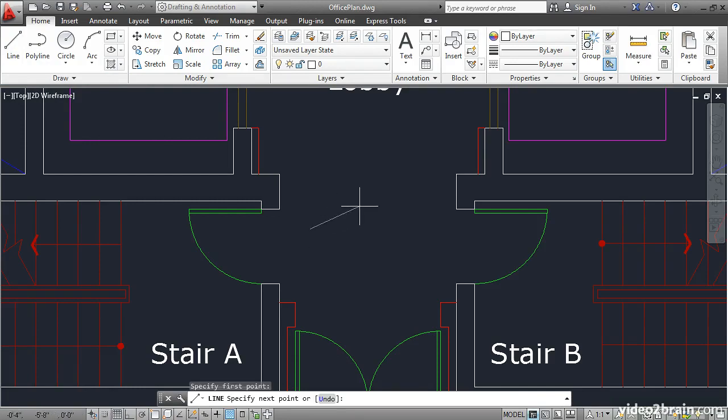Then go ahead and type in a value like this, 3 feet, using the apostrophe symbol next to the Enter key, and then type 6-1/2. What this means is 3 feet 6½ inches. The dash is necessary as a delimiter between the inches and the fractional inches. Without it, you'd either have 61 halves, or you'd have a space which would terminate this part of the command.